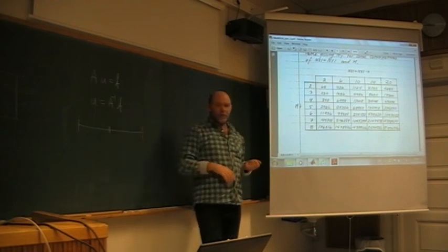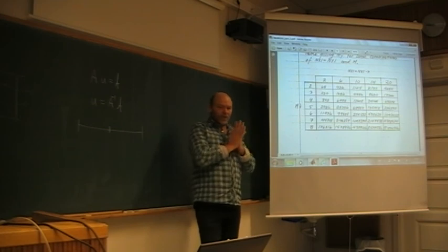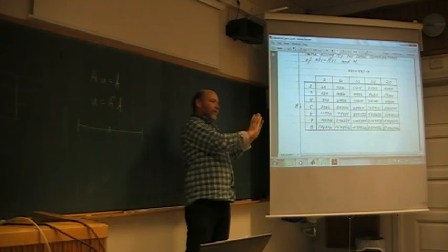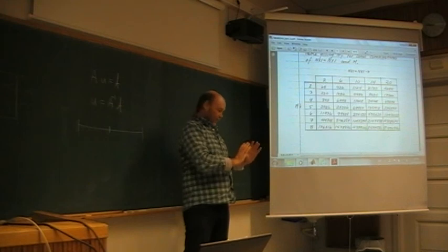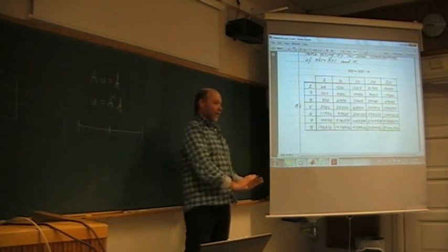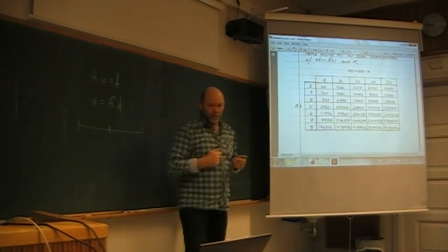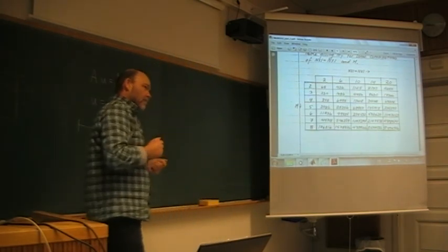I have an example for it as a reference. I played around with it once, and it was a little bit strange, because that was a turbulent problem, so I had a DNS on the fine mesh. Then on the coarse mesh, I had to use a large eddy simulation. And if I had gone to coarser meshes, then I might have had to use K epsilon. That's possible, actually, yes. But I'll come back to that example. There's a reason for it. Yeah, that's a good question.